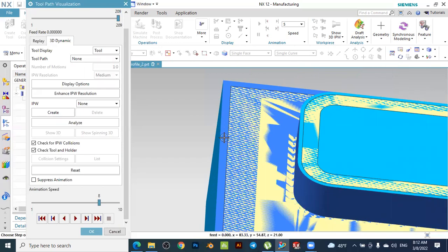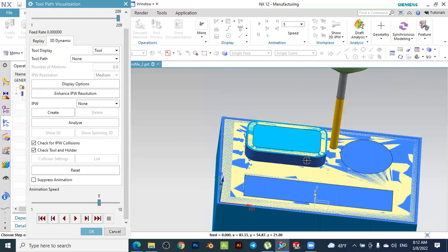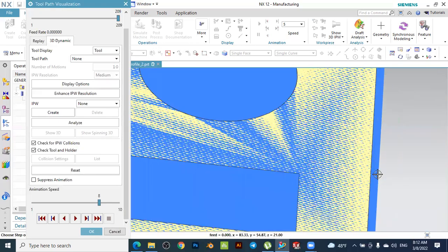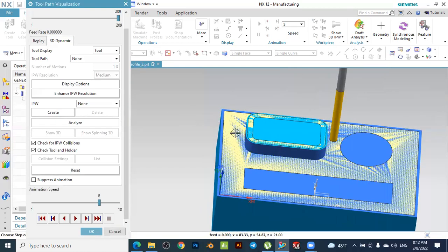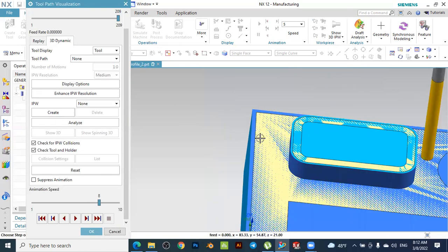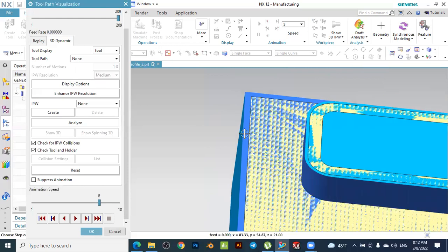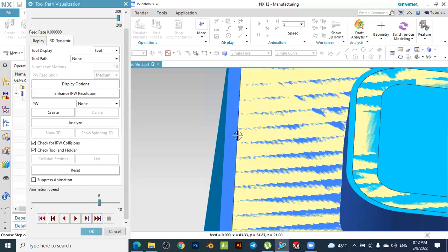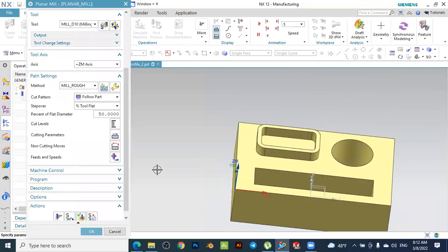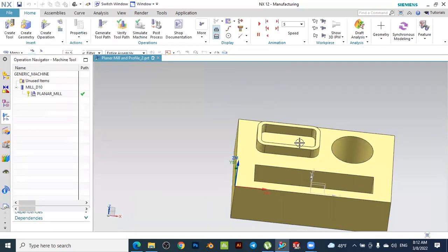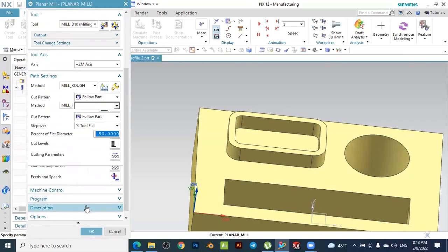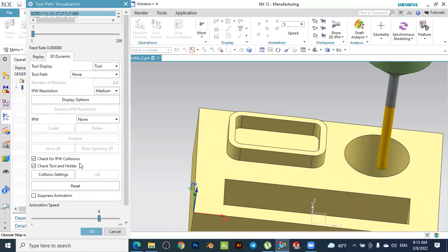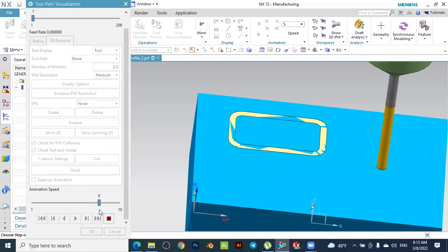Since we have the stock, which is 2 millimeters here, it is still remained because we only removed the material until this surface. In the next tutorials, we will also see how to remove this stock value of 2 millimeters. Now, as a next method for the cases, let's see the result again. Just for clarification, generate it.